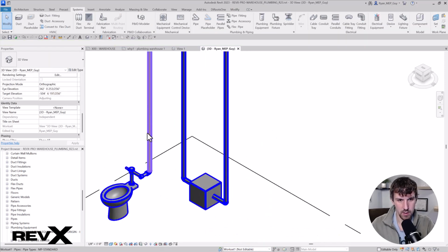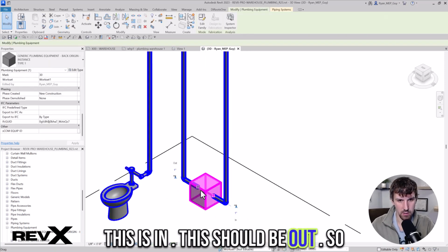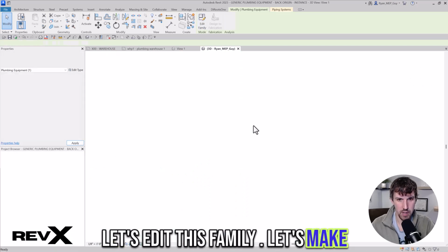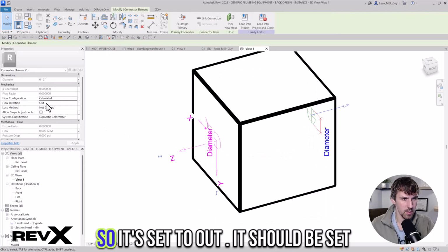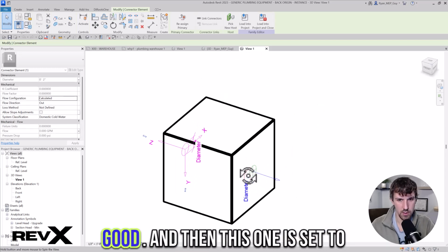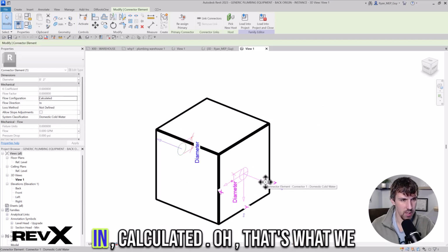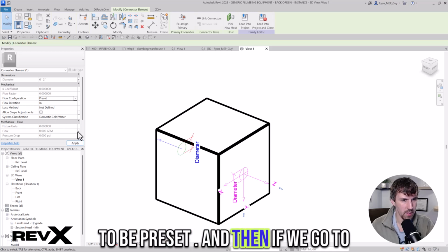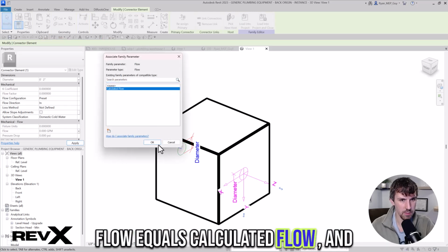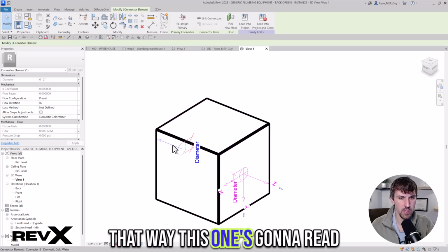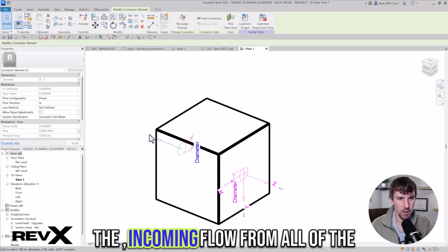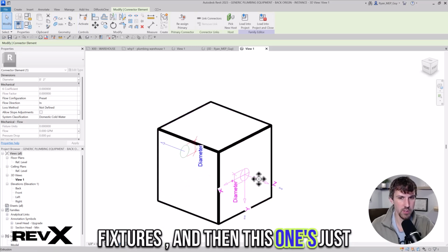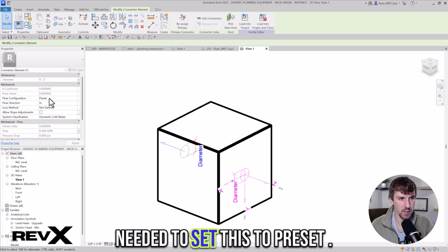All right, so this is in. This should be out. So let's edit this family. Let's make sure our out is out. So it's set to out. Should be set to calculated. Okay, that looks good. And then this one is set to in, calculated. Oh, that's what we did wrong, maybe. Maybe this needs to be preset. And then if we go to flow equals calculated flow, that way this one's going to read the incoming flow from all of the fixtures, and then this one's just going to be equal to that. So we needed to set this to preset.